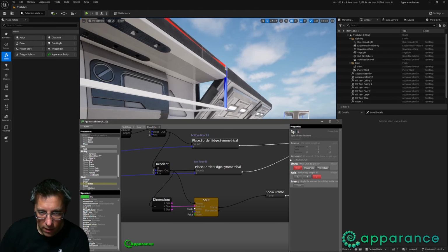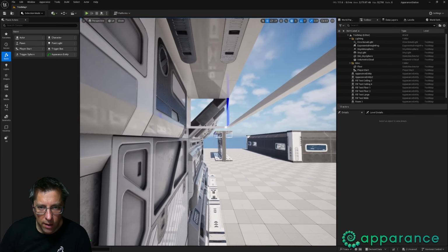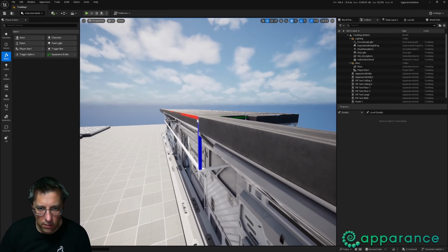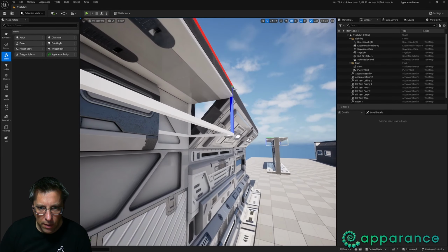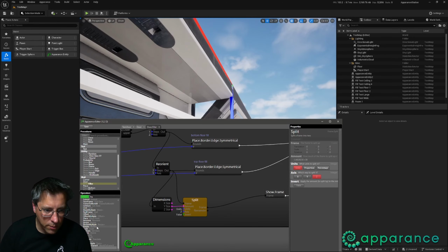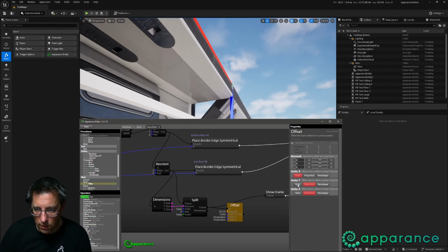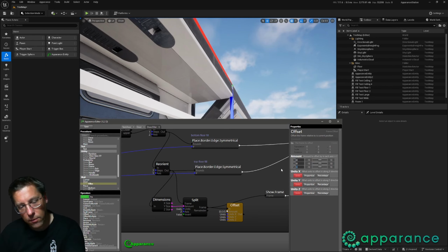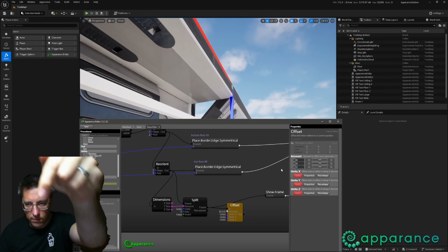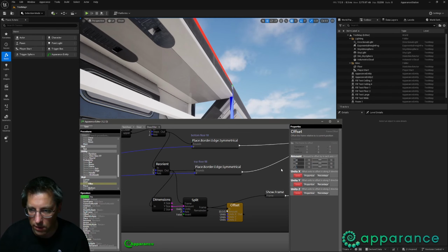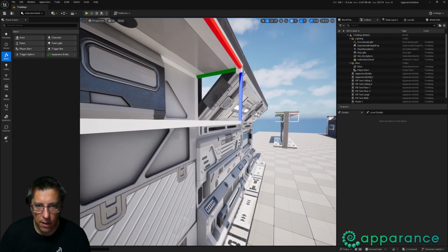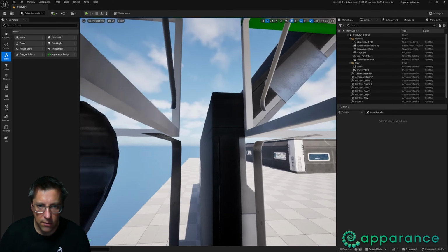There you go, so that should be a square. Yeah, that's a square section, but it needs to come down by this 0.25, so that's just a simple offset, which we can do here, like so. We're offsetting in Z, and because the origin is at the top, Z is down, so we just need to do positive, and bang, that fits that corner nicely.